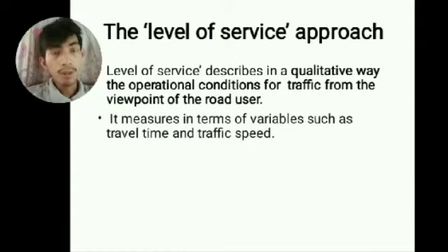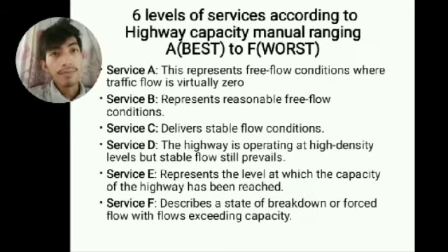The level of service approach. A level of service describes in a qualitative way the operational conditions for traffic from the viewpoint of the road user. It is measured in terms of variables such as travel time and traffic speed. There are 6 levels of service according to the Highway Capacity Manual, ranging from A as best to F as worst.